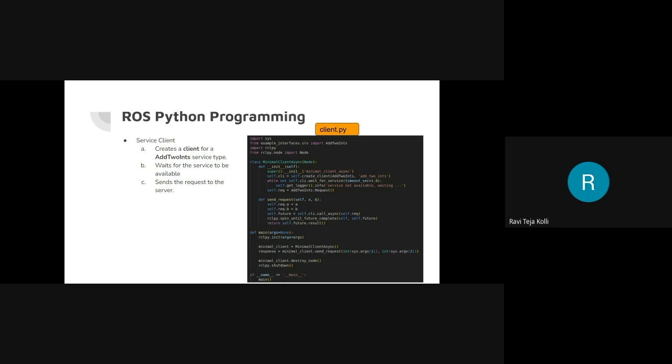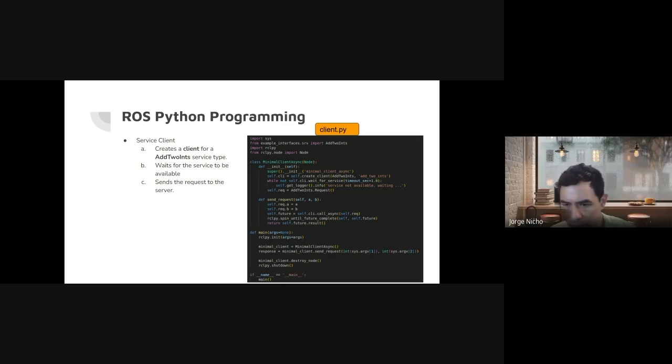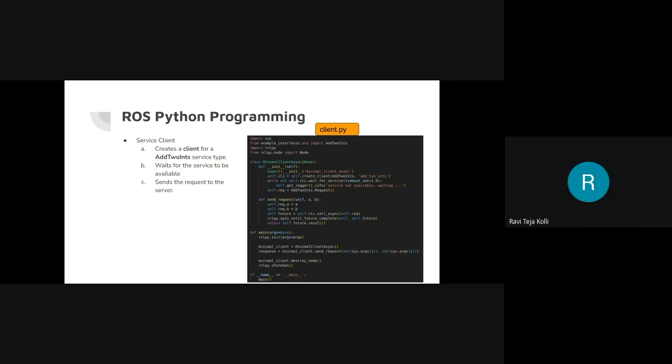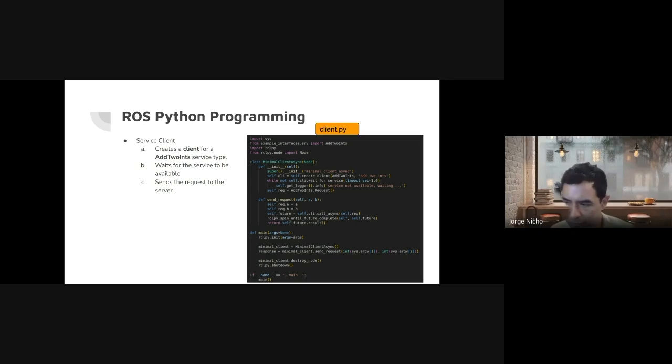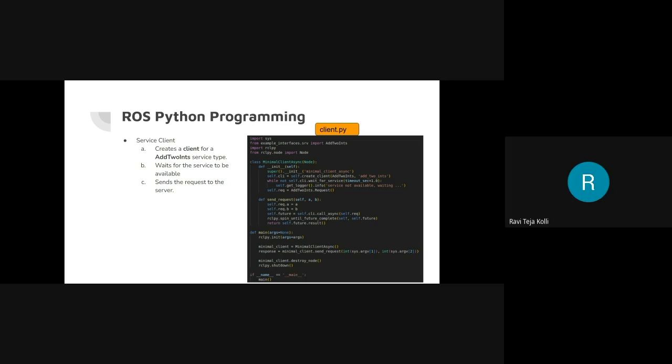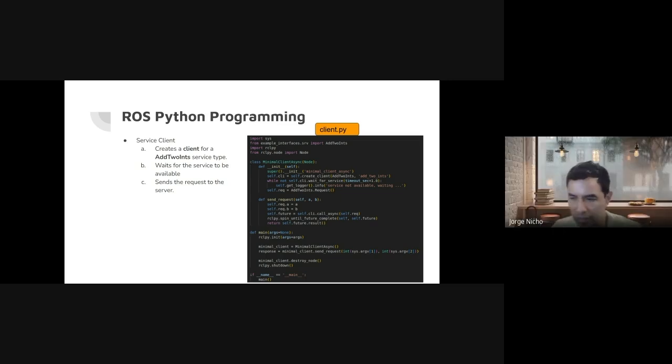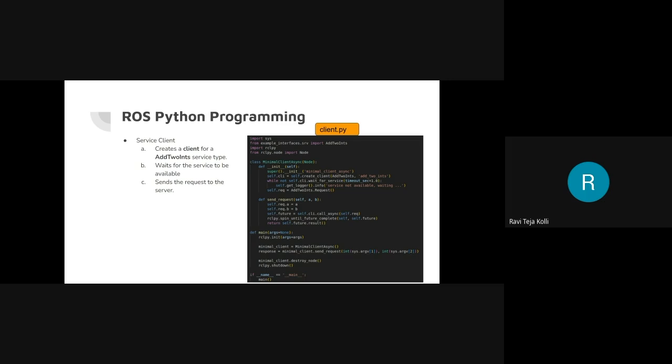If you give your TF coordinates in the ROS simulation, is that going to work, just for the simulation part? As long as it is reachable by the robot, it should work. Right. So it has to do with the robot's ability to reach that position and orientation. If it's feasible within its physical parameters, it should be able to reach that, or at least move toward it. It should be able to give you a valid pose for that. Okay. Thank you.